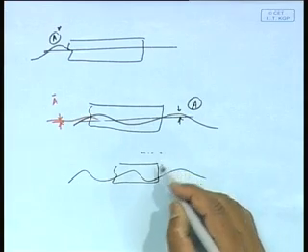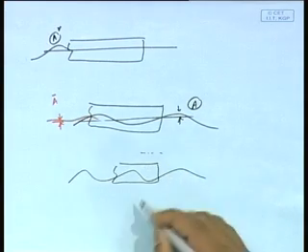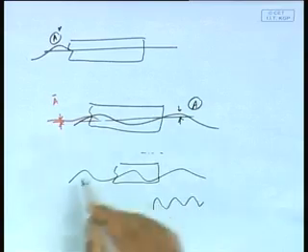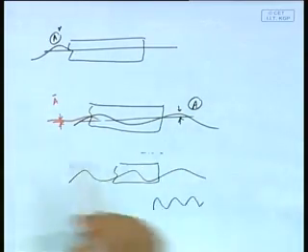Why should it drift? The first order response tells me that the surge motion is like that. That means if it goes down 1 meter, it should come back 1 meter. It should be oscillating about one point. If you leave a ship or a floating body on the water, according to my first order theory, if it went down this much, it comes back this much. It is oscillating, so it should not be drifting about a mean position.